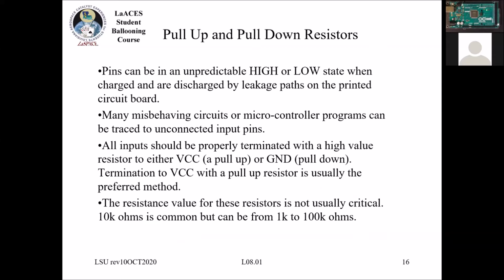Right, so like I just said, pins can be in an unpredictable high or low state, depending on a lot of hard to know variables if they're not connected to anything. So if you have something that's behaving weirdly, one of the causes may be that the input pins that you're using are not connected to anything, they're floating. And because of that, you want to, like I said, use a pull-up or pull-down resistor.